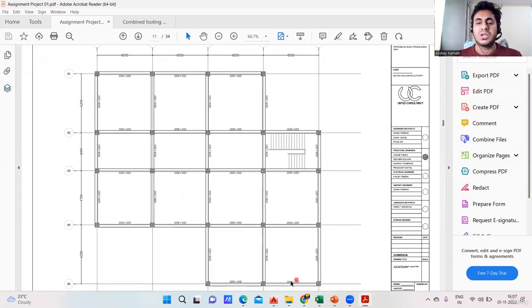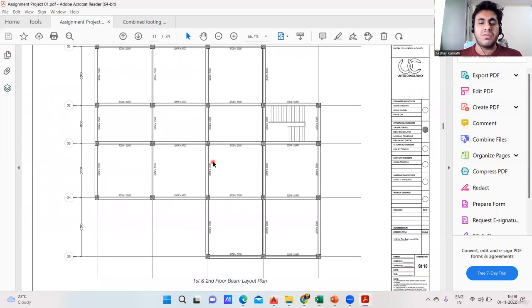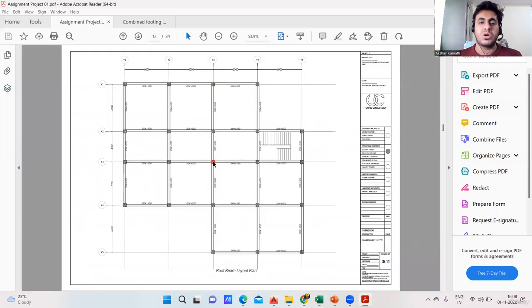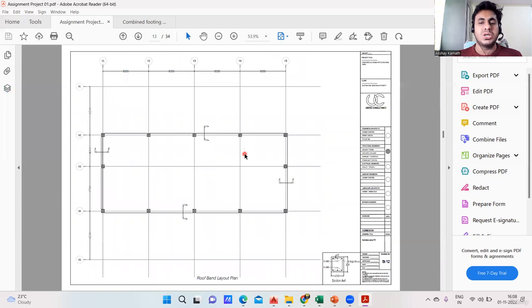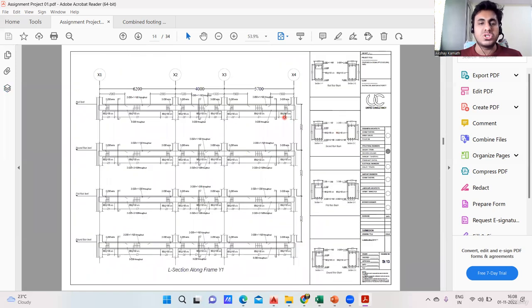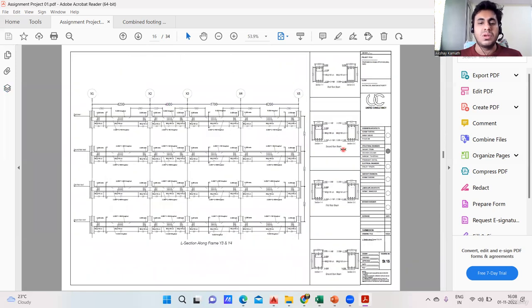Everywhere it's outside shuttering, I mean outside shuttering will come, beam bottom will come, this part will be inside shuttering, and here everywhere it is inside shuttering on both sides. Slab thickness, if they haven't mentioned, you assume it as 150, not an issue. But usually they'll mention it, okay? You don't have to assume. Usually the slab thickness and all will be mentioned.